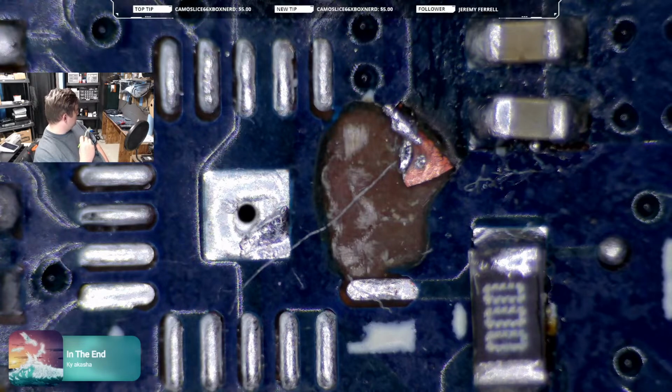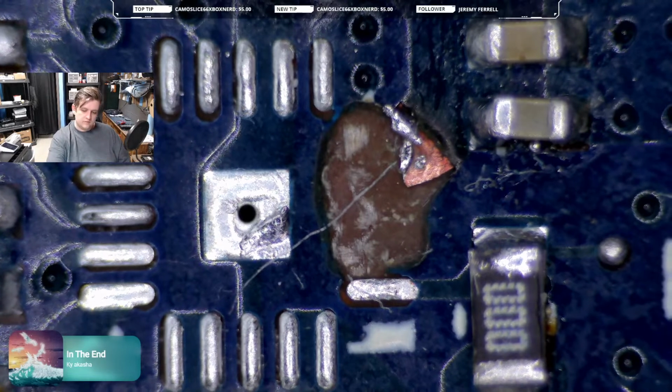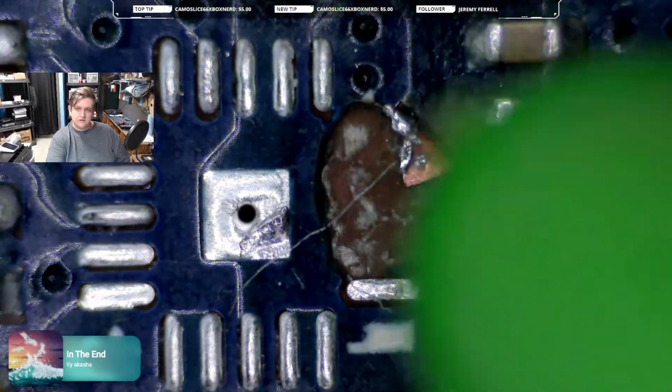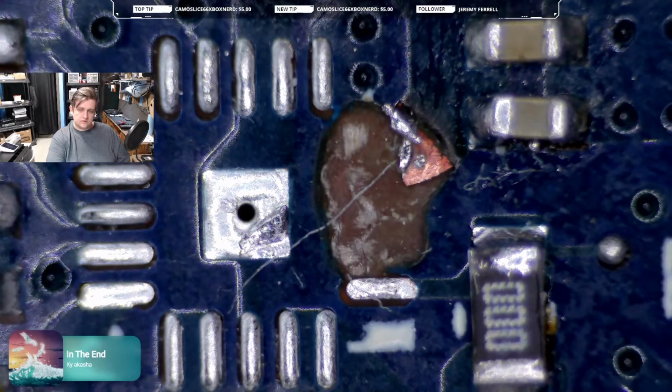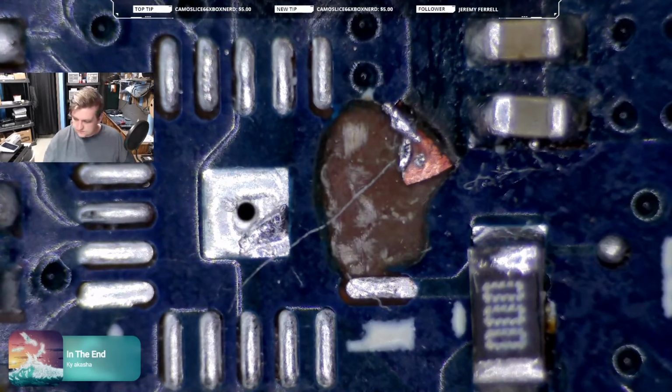The chip is in charge of stepping down the DC voltage from the power supply. The power supply takes the AC voltage, converts it to, I don't know, 17 something volts, and plugs into the system. While the system runs, it takes that voltage, disperses it how it needs to, and to get a 3.3 volt current, it goes through this chip here. And because the power supply was bad, it sent too much current to the chip and killed it. That's my theory. I could be wrong.